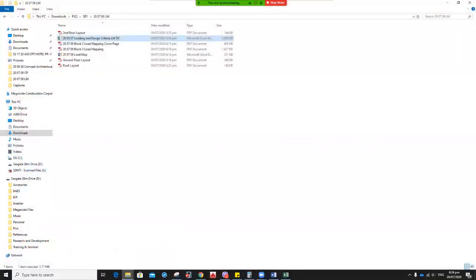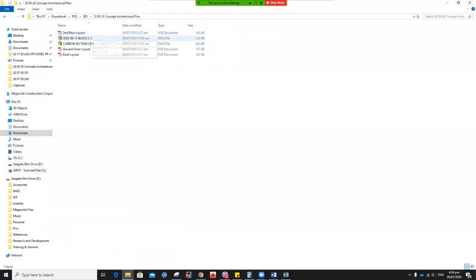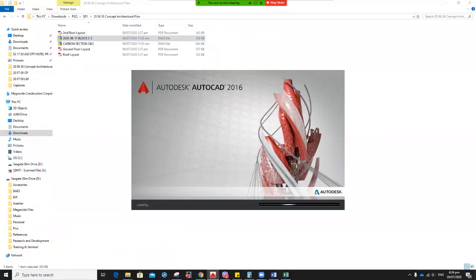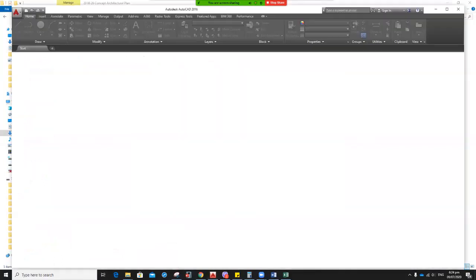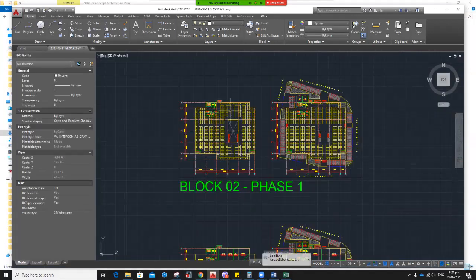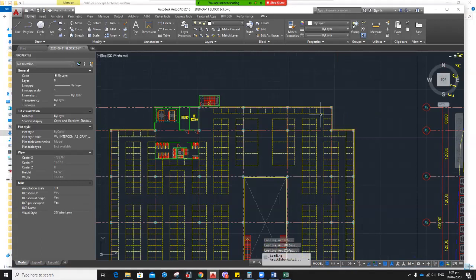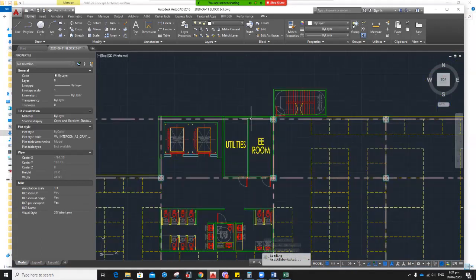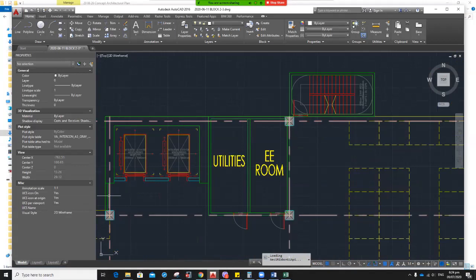I already closed it. I'll open the architectural plan. Let's see the block 2 carbon and this one. The floor plans. Let's open the floor plans. Since these walls are beam loads, we didn't reflect them in the floor load or the load mapping, and also it will just be very small. So we will be using those walls here. If you remember, we put a column here, and then we frame this one. Then we will be using walls here in this portion.